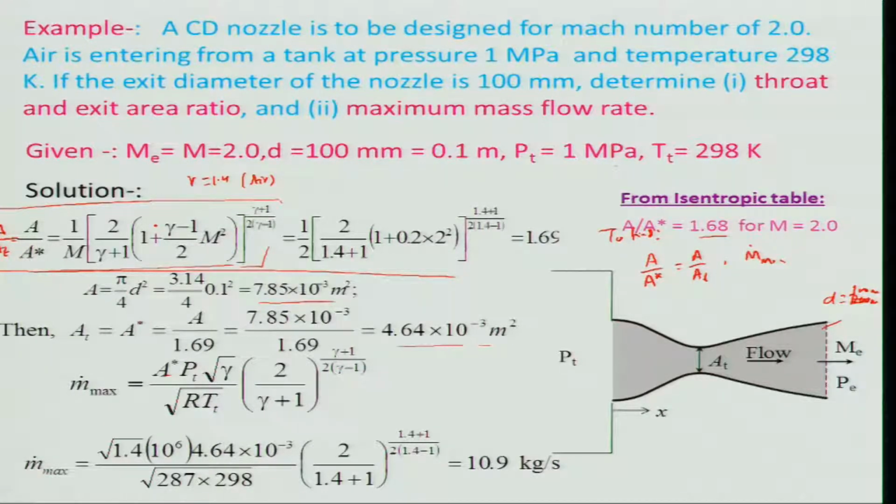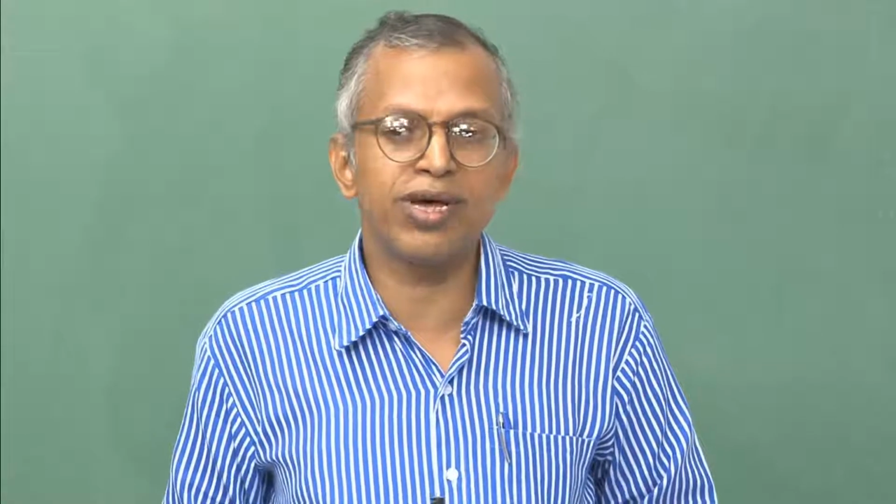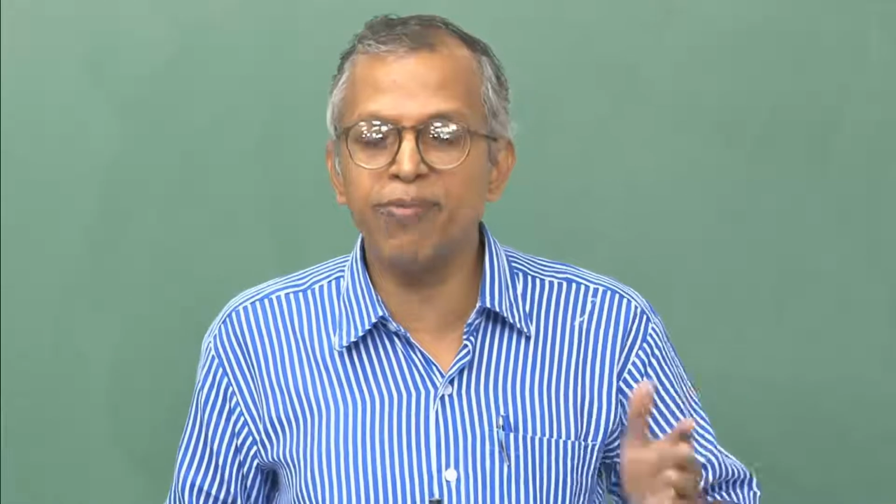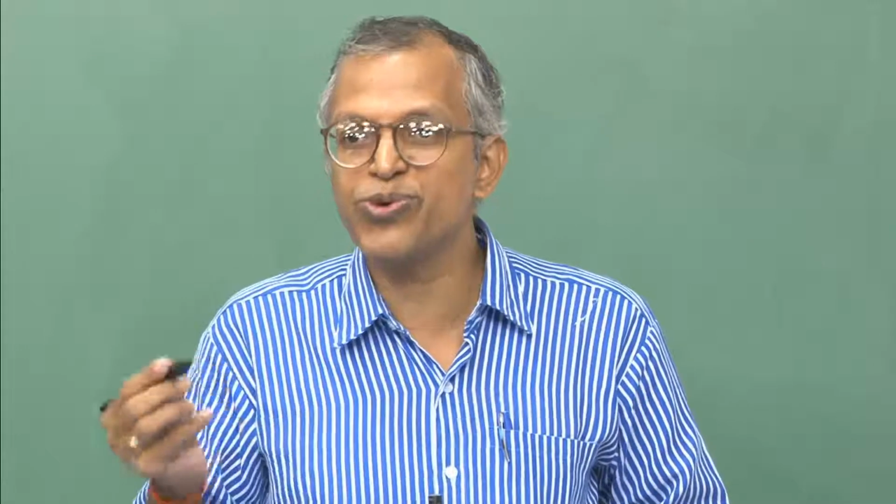That is again an approximation. So, we need to go for a table where I can use those values, because I can put various Mach numbers and get A by A t and P by P t and other things, and then use them. That is one way of solving this, unless of course a computer is at your hand. In earlier days particularly, computation was not that easy to do, so people were using the isentropic table. Therefore, there is importance in looking at the isentropic table.